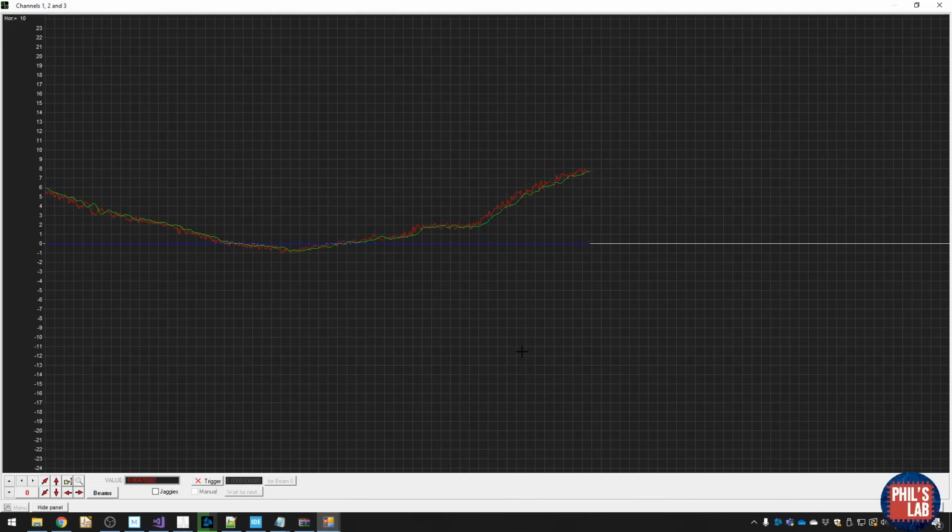If I just move it like that, you can see it follows it quite nicely. If I just let it stationary, another important point is that the DC gain is the same. So I'm not moving it, and we want the values to have the same mean, which they do, so that's good. But as you see, if I start increasing the frequency of oscillation, you can see that actually the green curve lags behind the red curve. So the filtered data lags behind the raw data, and this, of course, can be problematic.